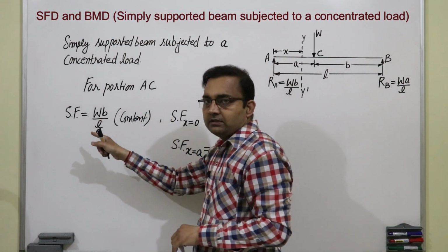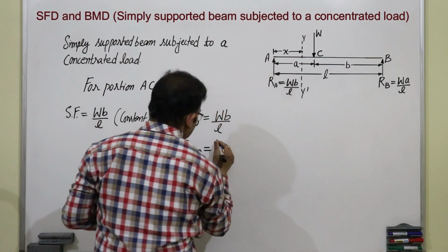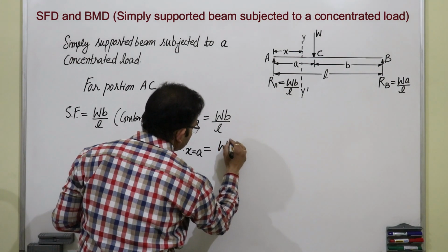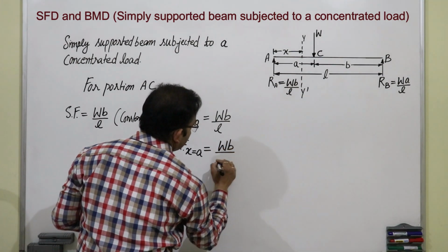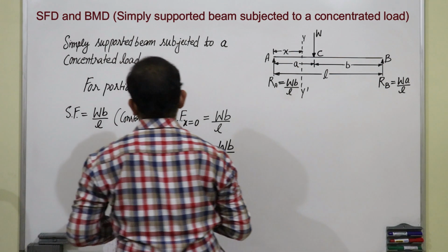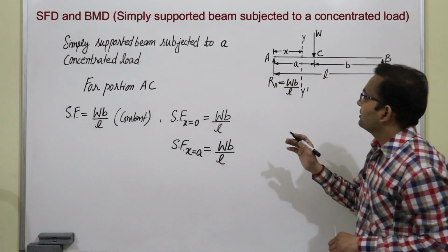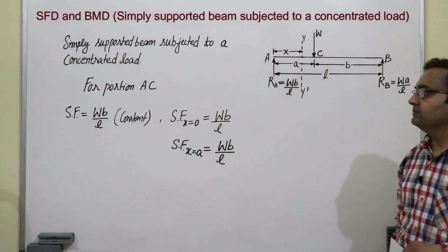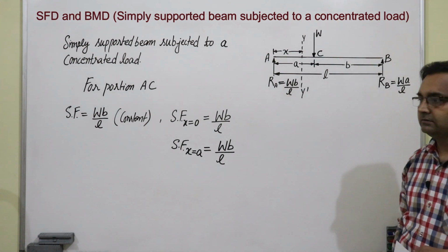There is no x in the equation, so it is again the same, WB by L. So, from A to C, shear force is constant.